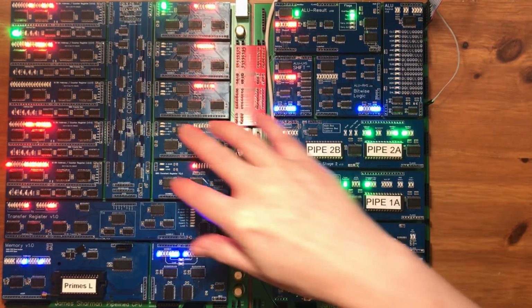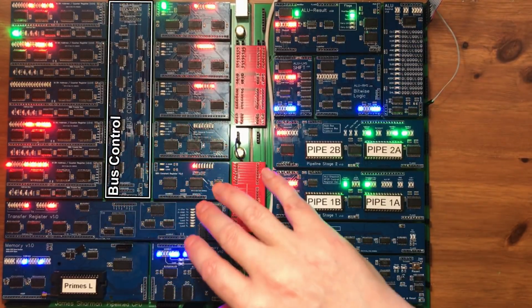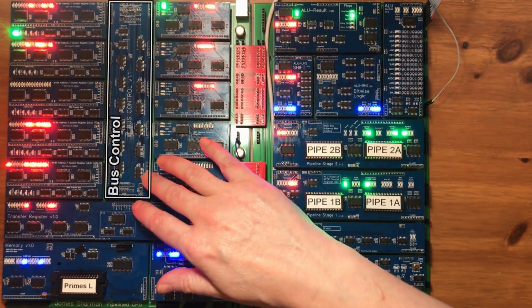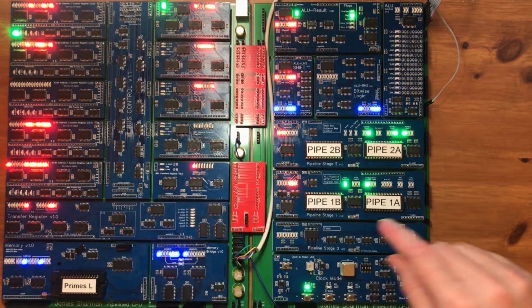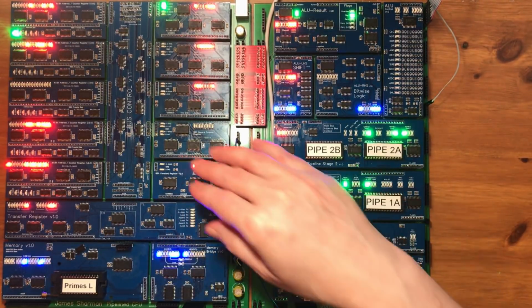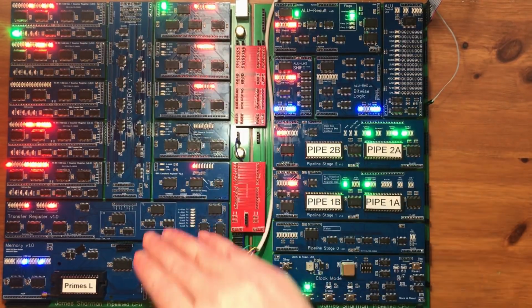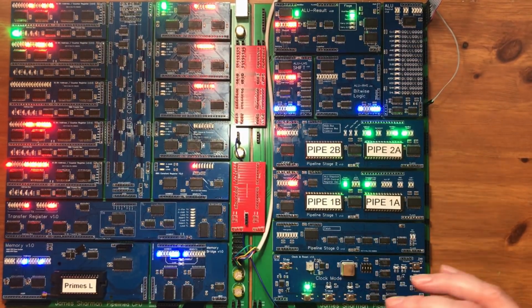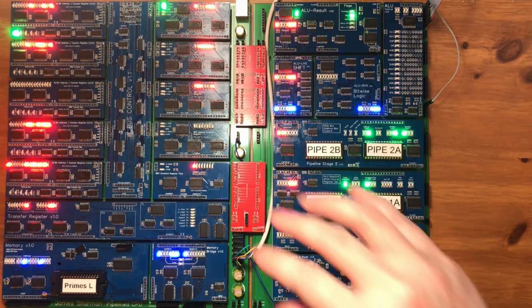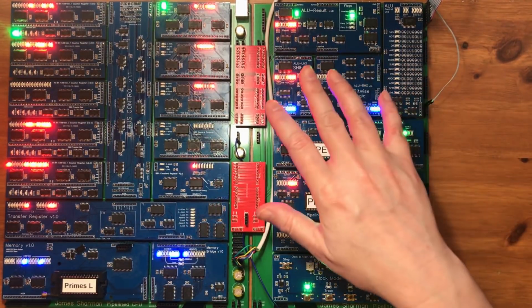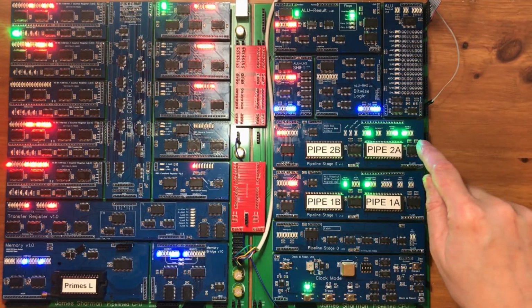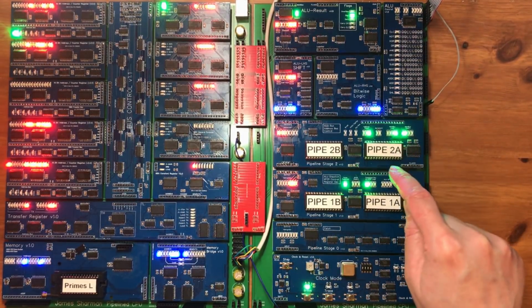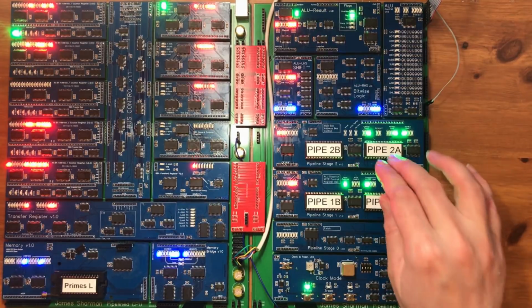And that's where this bus control device comes in. What this is doing is using the 3 to 8 line decoders to turn index values into a much larger number of control lines. So for the main bus, I've got 16 assert lines and 16 load lines, which are driven by 4 bits each coming out of pipeline stage 2, and I think that's the bit you're missing.